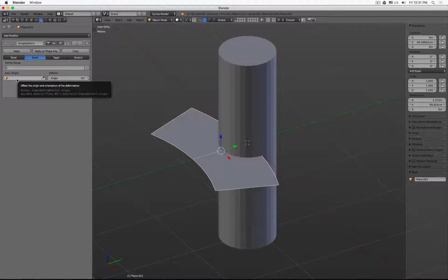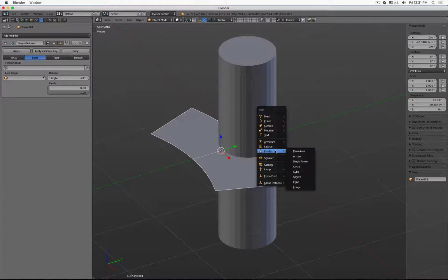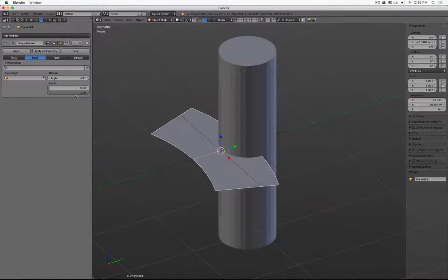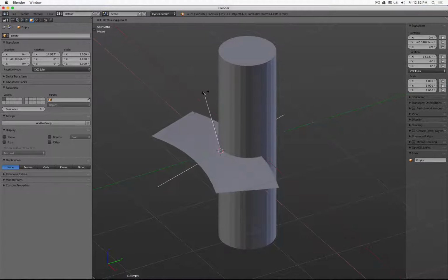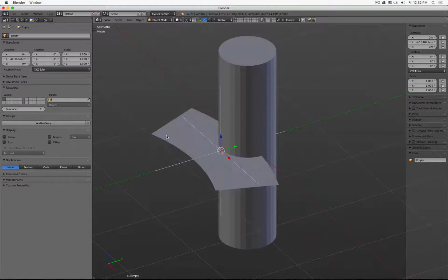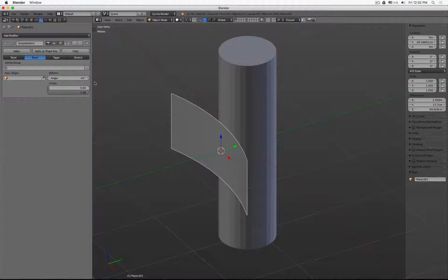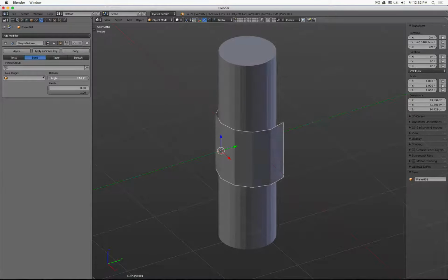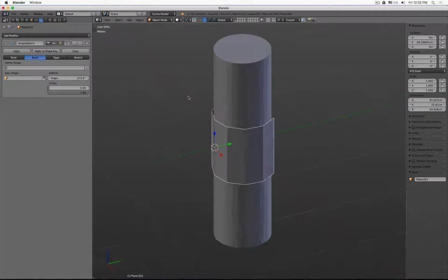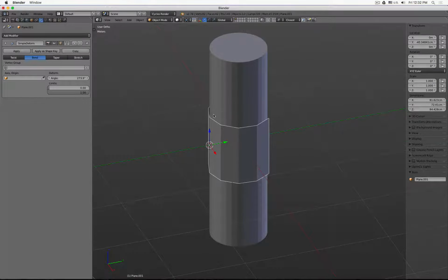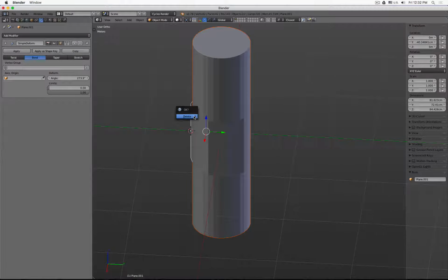We can use a different object, for example, for the axis. So let's say here, I think this will work that way. And then if we rotate this one, see, there it borrows that orientation. So that works. But before I do something that complicated, I simply rotate my object in object mode, or in edit mode, so that the mesh is perfectly aligned to the z-axis. So this makes sense.